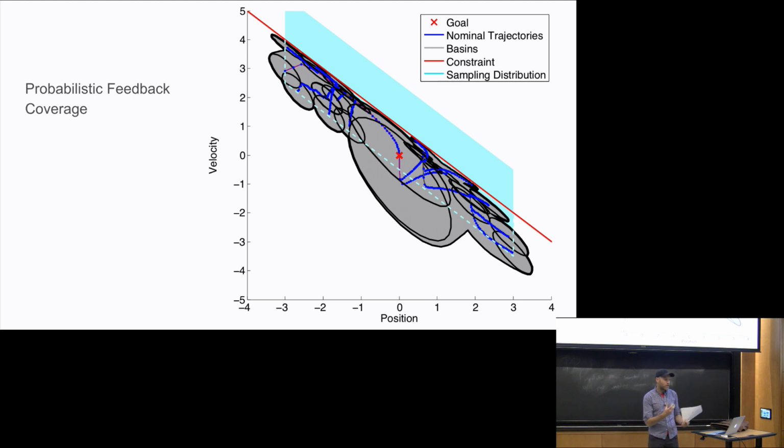So again, you don't have to use LQR, but LQR has the property, right? Think about what was missing from the Burridge part. We need not only to compute the region of attraction for a given skill, but somehow a recipe for when there's a place I want to get to over here and a set of controllers that I can pick from with some parameters: how do I generate a new controller that's going to land me inside my existing region of attraction?